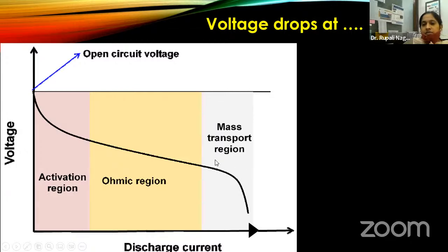Now, if you talk to people who are working with batteries, they'll tell you that whenever the battery is discharged to 33%, please put it to charge, and whenever it is 100% charged or 90% charged, please remove it from the charger. The reason is that when you overshoot these limits, you are actually making the battery work in these regions. And of course, the thermodynamics and the kinetics of the reaction tell us that these are reversible reactions. But if you operate them under the extreme regions